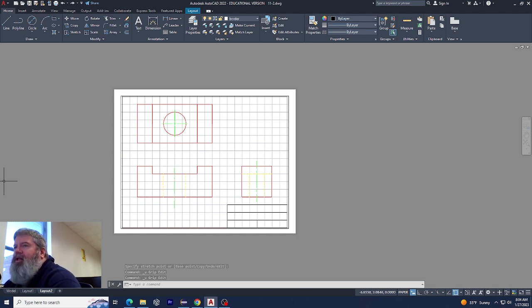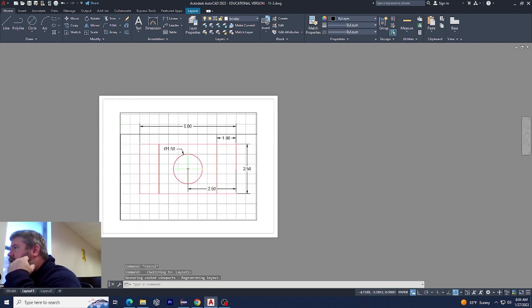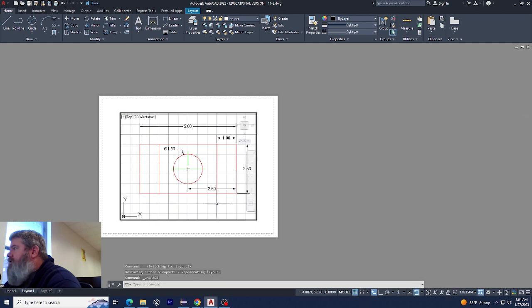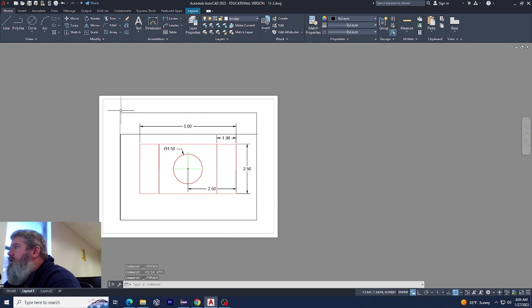When plotting a layout, all right, let's move on to plotting. So that's a really quick... oh, one more thing I wanted to show you in viewports. This is not how I want it to plot, like I said. So if I go to model space, I want to turn off the grid. That looks better. And then I take this, which is on the border layer.